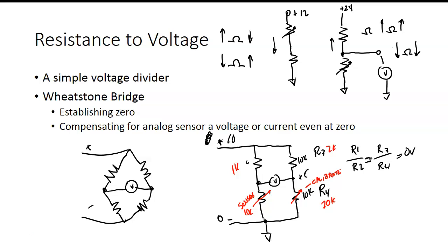With a voltage divider, you would do that. All it's going to do is, if the measurement goes up, the resistance is going to go up, or down. Well, is that minus 5 degrees or plus 5 degrees? We don't know that. Then we have to figure out what we call a transfer function for what these voltages mean. So this is the Wheatstone bridge. It can give us both a negative and positive measurement, it can compensate for temperature, and it gives us the ability to set a 0 reference.